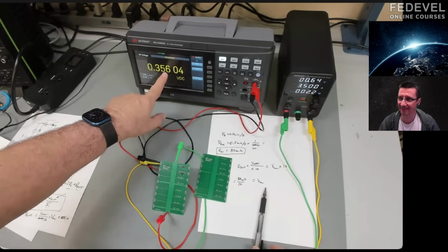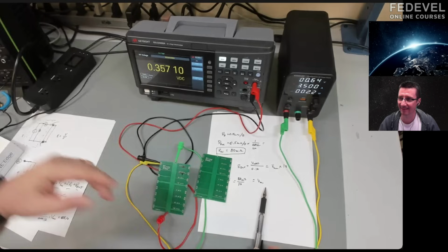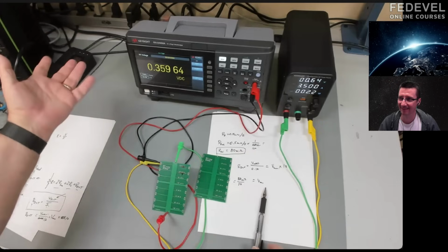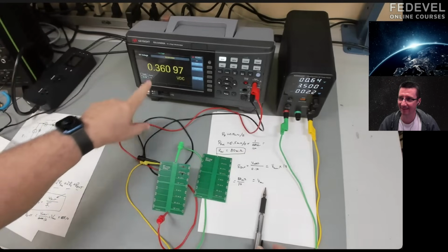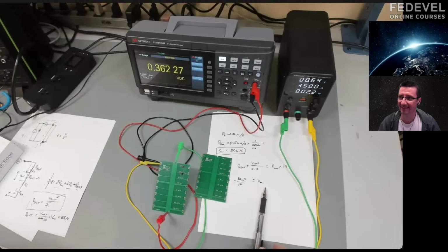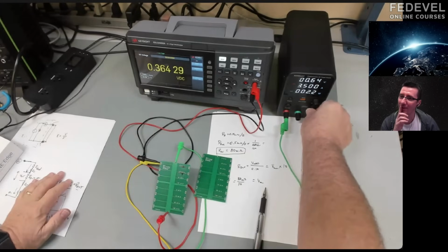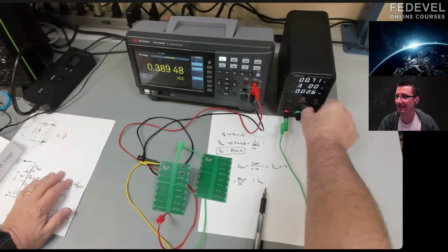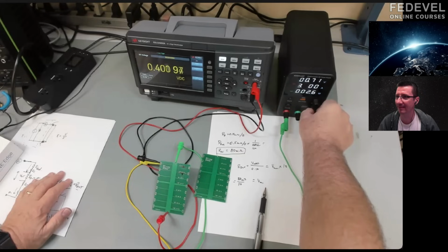It's getting a little bit bigger. The temperature is getting higher, the resistance is getting higher, the power consumed, I squared R, is getting bigger. It's getting hotter, but it's pretty stable. Let's increase it some more. I'm curious to see how the resistance will go up when we reach thermal runaway. So here's 3.6, here's 3.7 amps, and you can see it starting to increase faster.